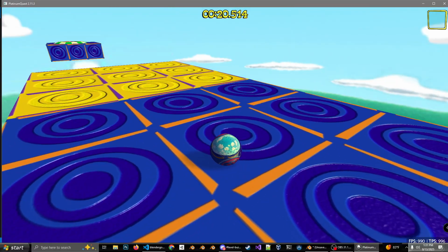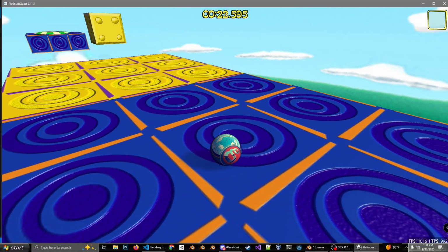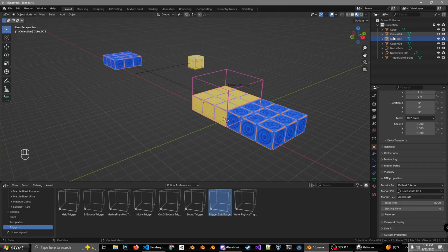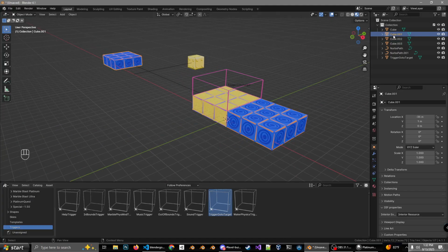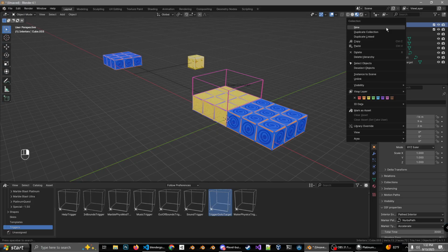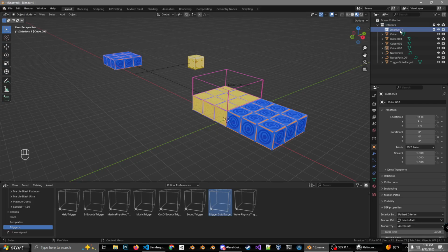Oh, how could I forget? There is one more tip I'd like to give. So let's go back to our Blender project, and you will notice that this could probably get messy really fast, and the easiest way around this is collections. As you can see, all of this is under a collection called Collection. If you double click this, we can name this Interiors. If we do New Collection, we just click New, and you'll get a new one called Interiors 1.